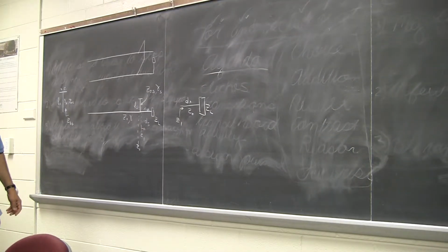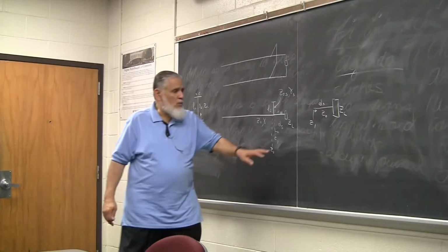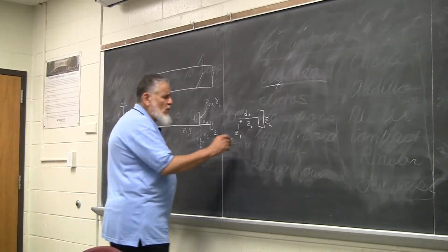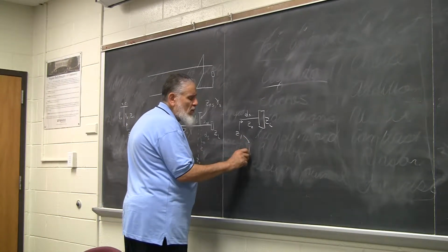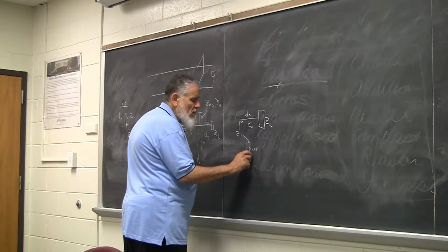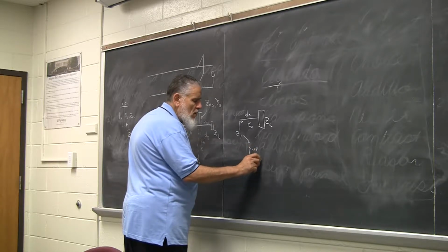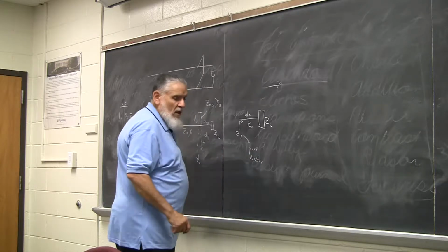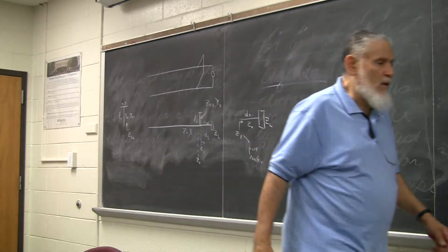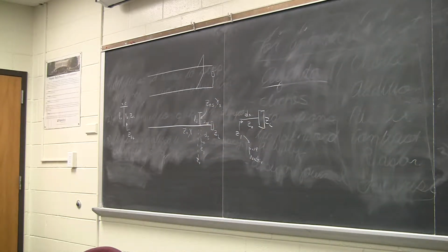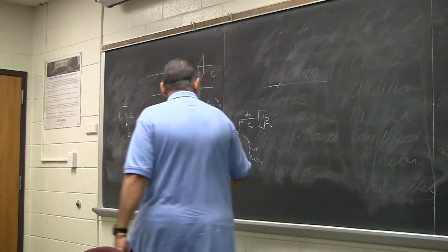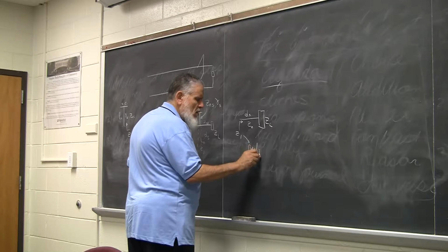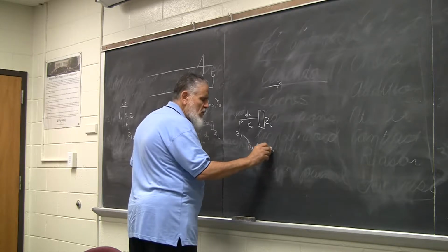So how do we do that on the Smith chart? We do this one first, and then we do this one next. So Z1 is supposed to be pure reactive. And the resistance, I'm sorry, not pure reactive. Let's say the right thing here, right? The real part is matched.